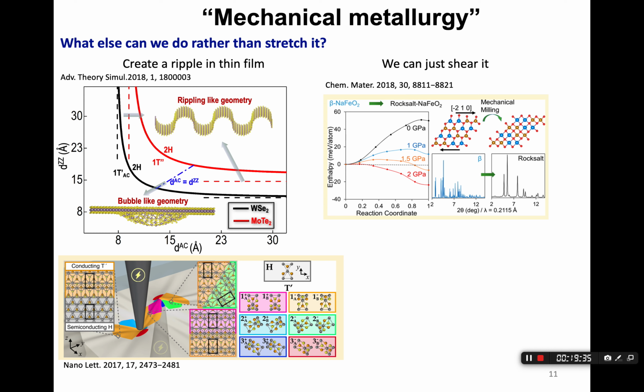Experimental results are shown on the right side. The XRD tells you that there is indeed a phase transformation if you do this ball milling synthesis. That is the evidence that just mixing and heating it up is not the only solution when we synthesize ceramics. Sometimes ball milling conditions can create a mechanical deformation to the particles so that the phase transition will also happen because of the instabilities under the mechanical deformation. So that's pretty much the concept of mechanical metallurgy.